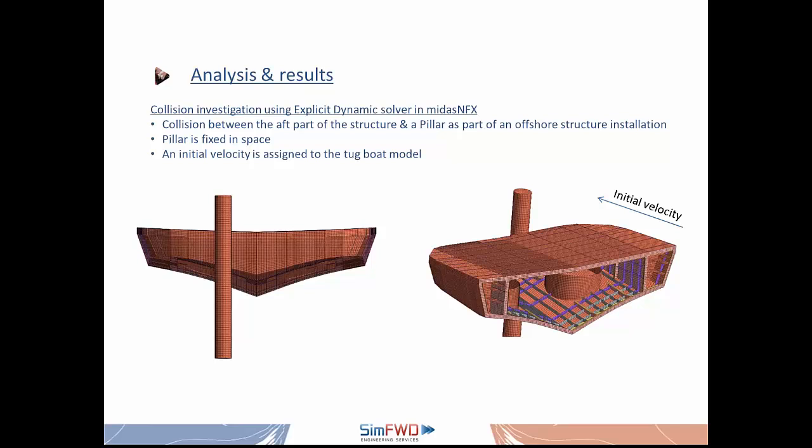We have used the same IGS model for both software in order to define the structural geometry and also the CFD computation. And then we have used also the same FEM model to derive the results for the static analysis. And now you can see that the same models, we can also use it for the collision investigation.